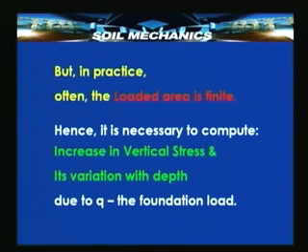Let us proceed further. So, as I mentioned, in practice very often this loaded area is finite, it is not very large, and therefore, we often need to compute the increase in the vertical stress and its variation with depth due to the surcharge Q, which is nothing but the load that the foundation is transmitting. So, this is merely emphasizing what I told, that it is the increase in the vertical stress that we are interested in.